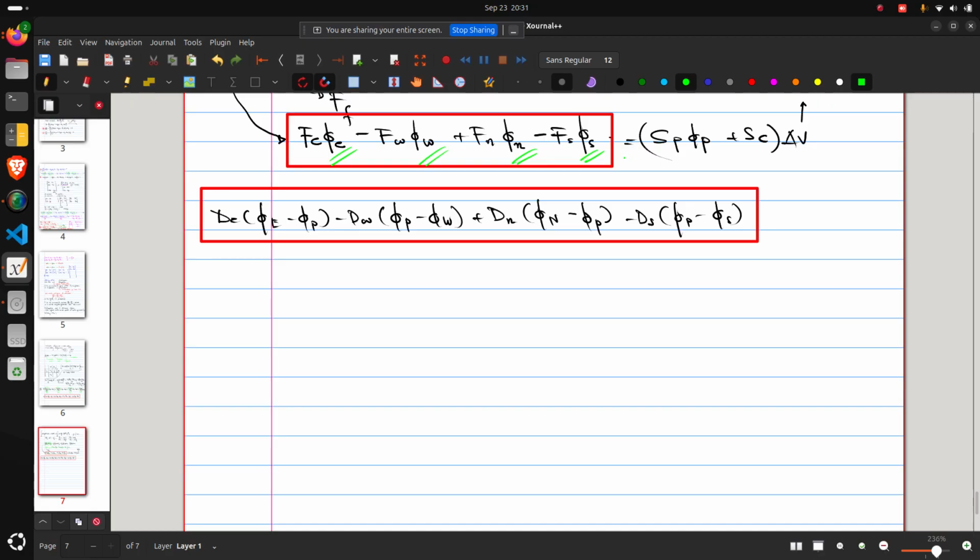This way we can get an approximation of the phase at the cell centers, at the phase centers. There are multiple other ways that we can apply. There is something called upwinding or downwinding. These will be covered later in the course. So we'll stick to the basic approximation, that is nothing but the average of the two cell center values, right?